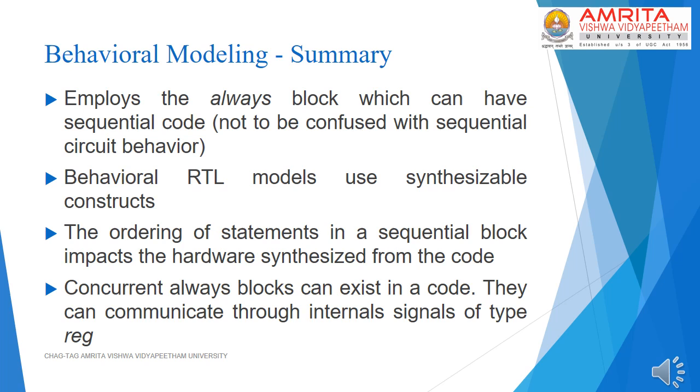Designers are expected to use synthesizable constructs while writing behavioral RTL models. The ordering of statements in a sequential block impacts the hardware synthesized from the code. Therefore, designers have to be careful to ensure that the statements are properly ordered so as to reflect the behavior that is expected from the block that is designed. Finally, concurrent always blocks will exist in a code. These always blocks will execute concurrently, and they can communicate among themselves through internal signals of type reg.